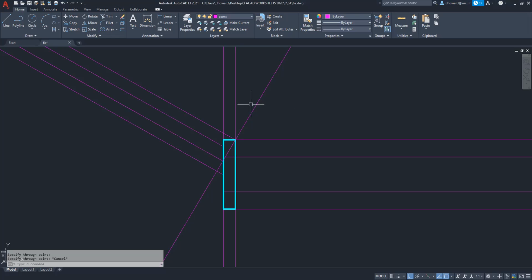So I'm going to offset this line 1.5 inches to that upper hole. So here we go. O, enter, 1.5, and bam, there it is. So that's the center line of the hole going through those. And then, of course, we have the radius, which is 3/4. So you can offset that guy as well, 0.75. And there's that. So now you have the final length. So we'll outline those guys. You have the object lines.